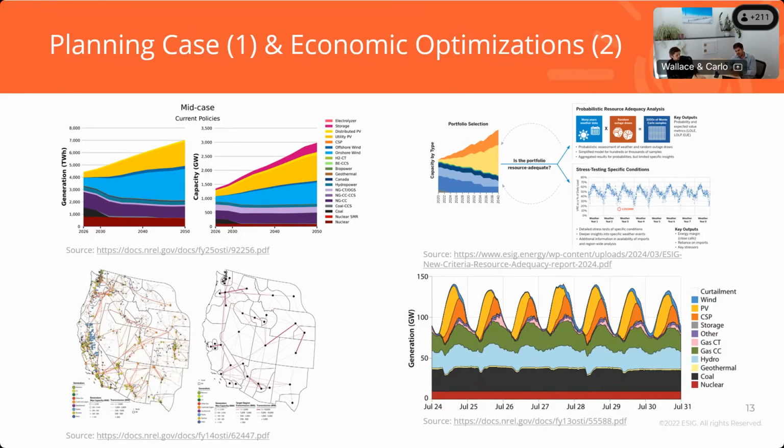But regardless, even if I have the information, the data, the knowledge, the tools to run resource planning models that have full detailed transmission representation, in other words, if I could run nodal capacity expansions, resource adequacy, and production cost models, there is still a lot of detail from a transmission perspective and from a reliability perspective that I am not capturing, because I do still have to simplify the way I represent transmission in my system.